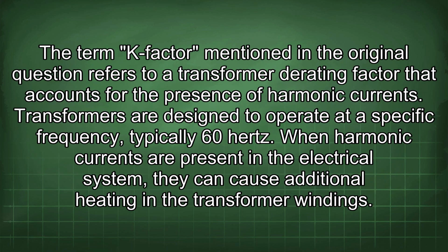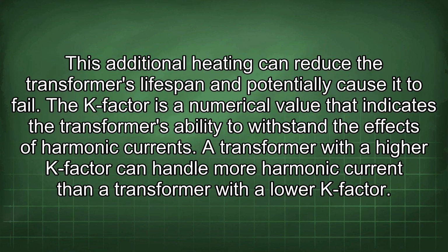The term K-factor mentioned in the original question refers to a transformer derating factor that accounts for the presence of harmonic current. Transformers are designed to operate at a specific frequency, typically 60 Hz. When harmonic currents are present in the electrical system, they can cause additional heating in the transformer windings. This additional heating can reduce the transformer's lifespan and potentially cause it to fail. The K-factor is a numerical value that indicates the transformer's ability to withstand the effects of harmonic currents. A transformer with a higher K-factor can handle more harmonic current than a transformer with a lower K-factor.